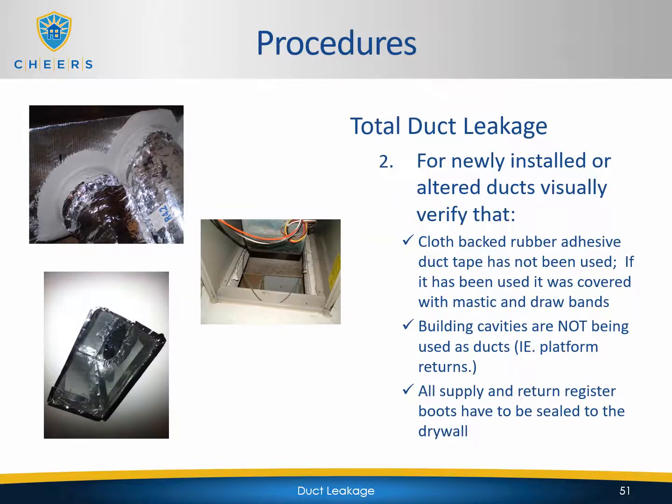You have to visually verify that cloth-backed rubber adhesive duct tape has not been used. If it has been used, it was covered with mastic and drawbands. Building cavities are not being used as ducts, for example, belly cavity returns or chases in the walls. And all supply and return register boots have to be sealed through drywall.